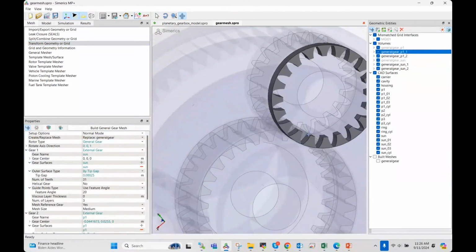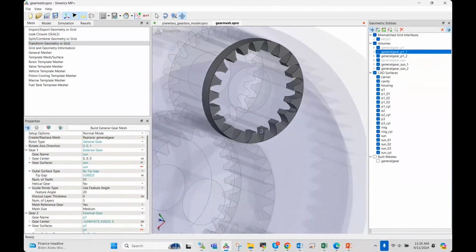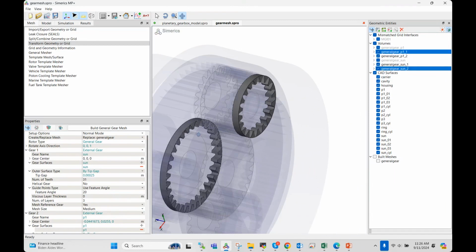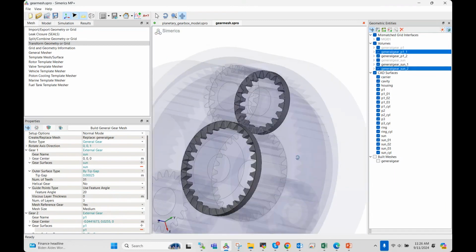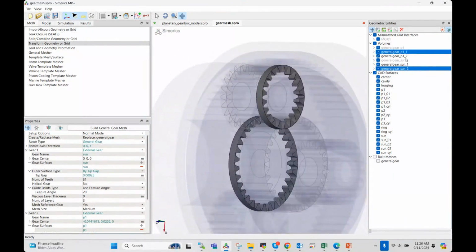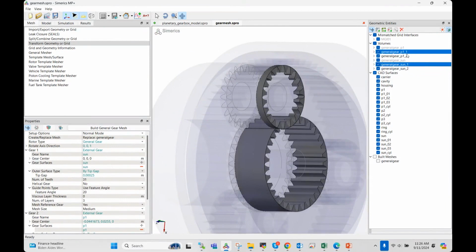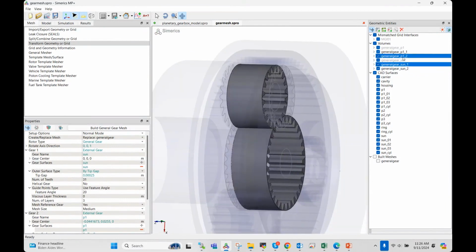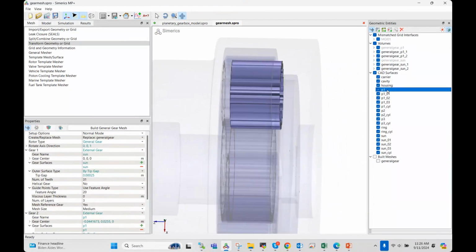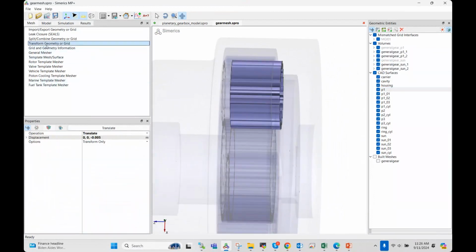The other zones, which are not common, it creates a mesh automatically for, for the sun and the planet. We don't need any special treatment for it. You will just see that it'll have 4 domains because there is a common intermeshing zone now, plus an extra zone for the planet and an extra zone for the sun. And this can be any which way. It's not limited to one direction.